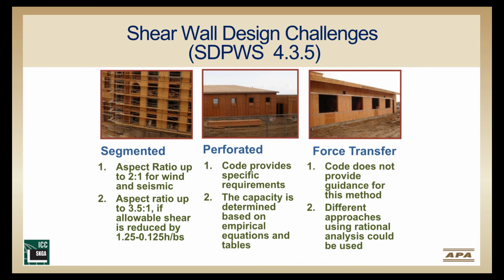But before we focus on FTAO, let's look at our full spectrum of shear wall choices per the special design provisions for wind and seismic, which is part of AWC's National Design Specification for Wood Construction. In SDPWS Section 4.3.5, it defines the different shear wall options you can use, such as segmented approach, a perforated approach, and force transfer around openings approach. We will compare and contrast these to begin, especially for those of you who do not do wood design regularly.